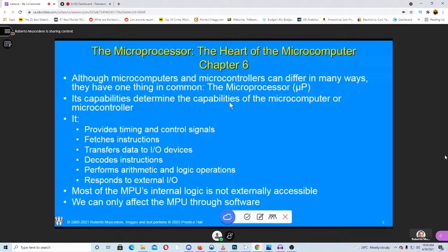I can't get it now, but maybe next day I'll show you. I don't know if you guys have ever seen the Arduino microcontroller boards, but there are some where they have a DIP package. You see this very large chip on there with like 14 or 16 pins, and they have some that are just little surface mount things about 5 millimeters by 5 millimeters. It's the same chip, just in a different package, and again, far less money for that version. But you can't easily connect to or probe the pins, or change the chip if you like. It's just not possible.